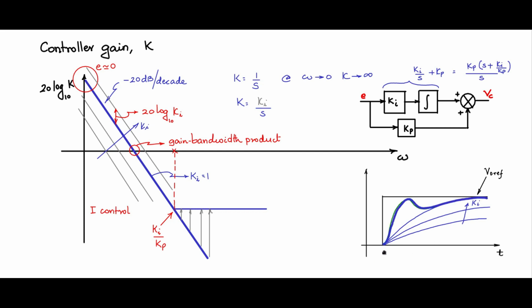So the whole response may look like this with a PI. Initially the P comes into the picture. The P is actually improving the transients, and then after the transient has passed, going to the steady state, the baton is handed over to the I control, and you will see a response something like that. So this way you try to include a PI controller.